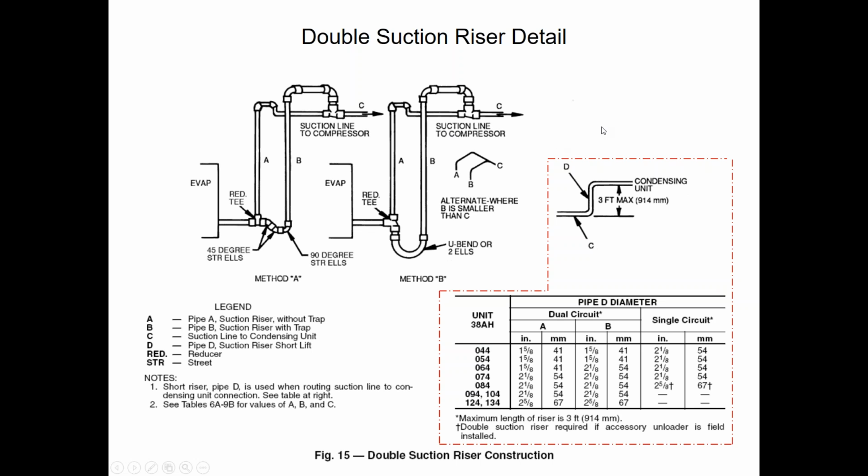So it's all about velocity all the time on your vapor pipe and your vapor lines, meaning both discharge and suction. Keep the velocity up. Even the evaporators come into play.